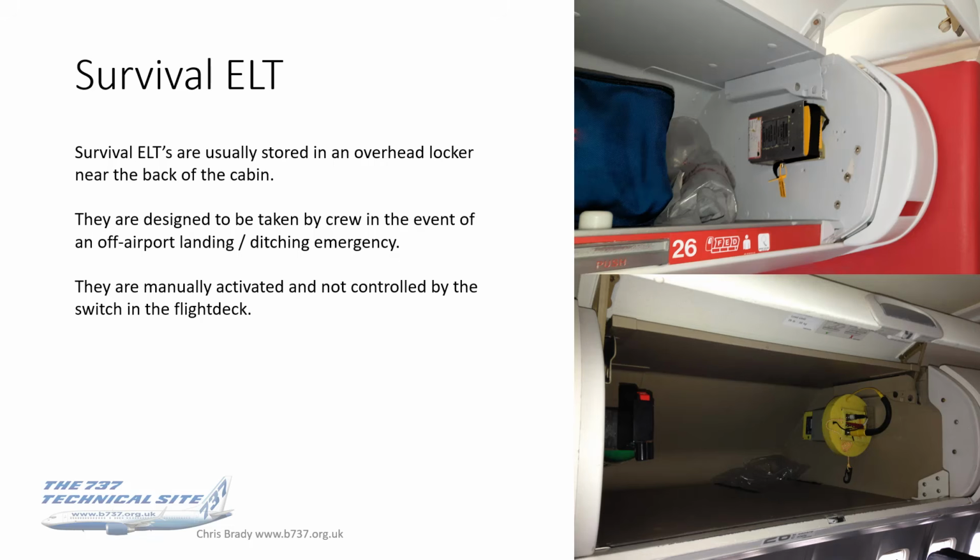These are manually activated, and they're not controlled by the switch in the flight deck. So just because it's an ELT doesn't mean that ELT switch in the flight deck will activate them. It won't. These are manually activated and designed to be taken with you if you have to leave and make your own way from the aircraft.